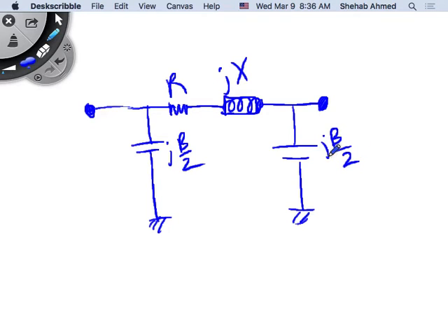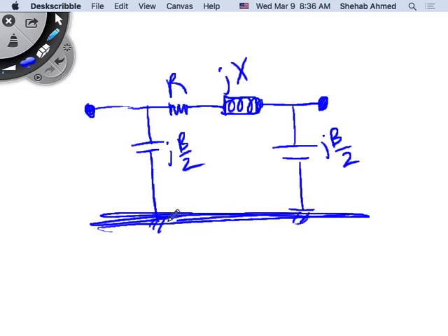Susceptance is basically the imaginary component of the admittance. So this capacitance represents the voltage difference that you have, a transmission line with a certain voltage level across it, and then you have ground or earth, right? It's like two conductors with opposite charge across them with a dielectric between them. So it's represented as a capacitor, right? We will go back and derive this after this chapter, but I prefer to do the power flow chapter first and then go back. So this is our equivalent circuit for the transmission line.